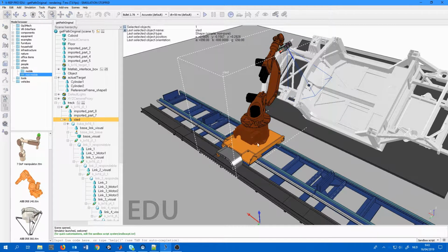But the thing is that it was quite a long trajectory, and you want a trajectory that is continuous and reachable by the robot. Actually, this kind of robot can do quite a lot, but inverse kinematics is challenging because of many collisions between the robot and the car frame here and the measurement device and the robot itself, so also self collisions.